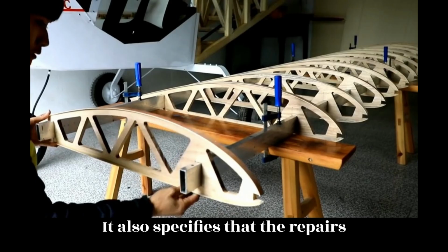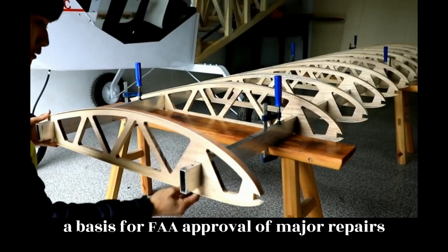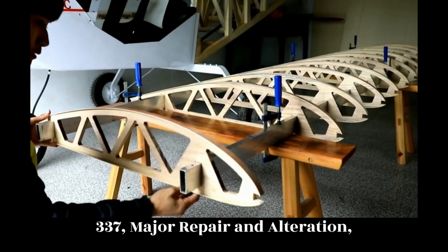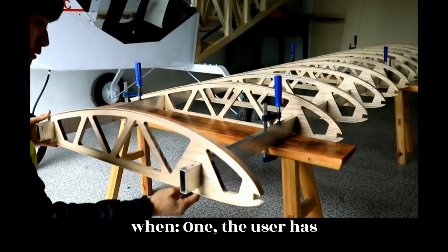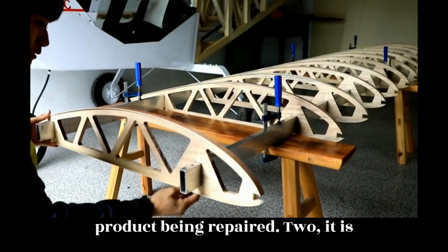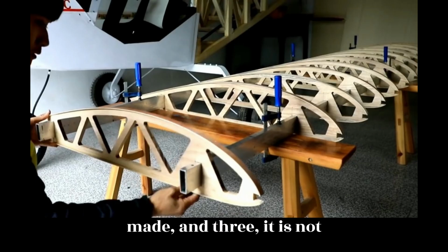It also specifies that the repairs identified in the AC may also be used as a basis for FAA approval of major repairs when listed in Block 8 of FAA Form 337, Major Repair and Alteration, when 1. The user has determined that it is appropriate to the product being repaired. 2. It is directly applicable to the repair being made, and 3. It is not contrary to manufacturer's data.